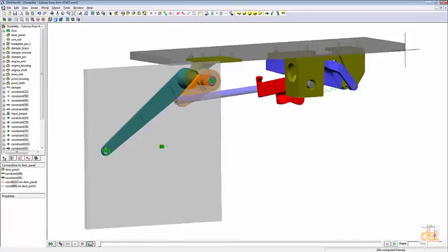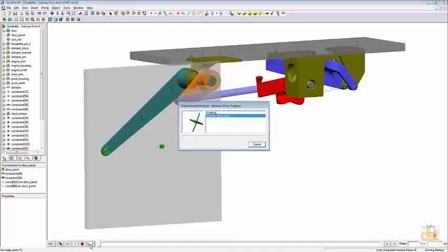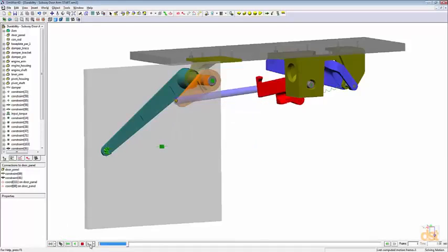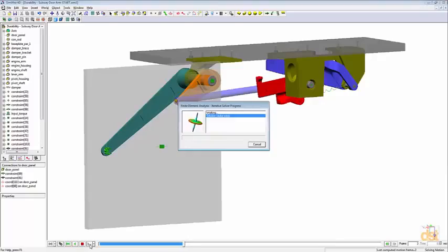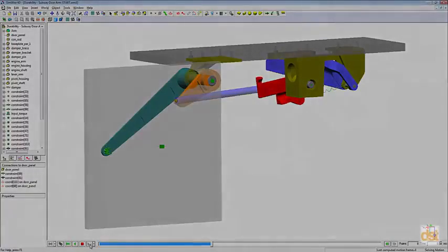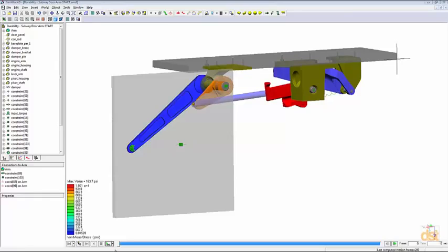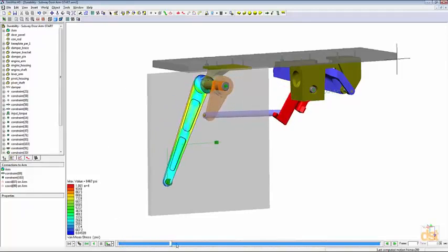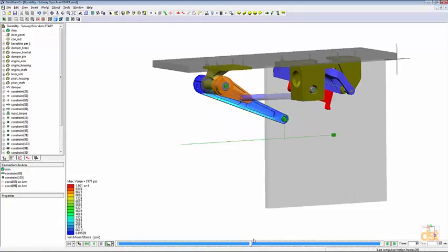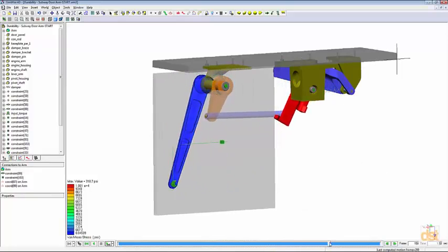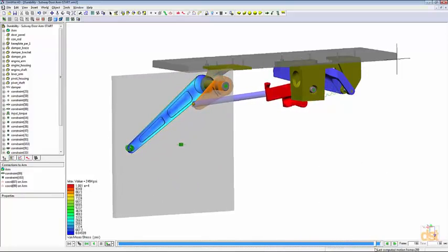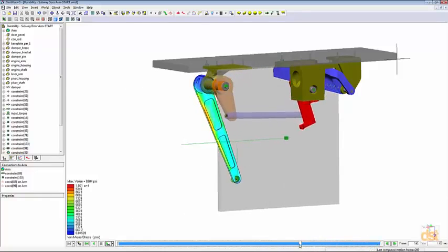We'll come down to the panel here and we'll click on the Motion with FEA option, and then we'll click on Run. Here we can see a simultaneous motion and stress analysis being done at every single time step. So we're back after running the simulation, and if we click on the playback slider button here and drag this through, we can see the entire range of motion and the stress resulting on the arm. This particular simulation took about 4 minutes using the time step that we specified.